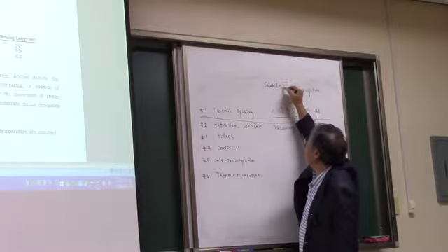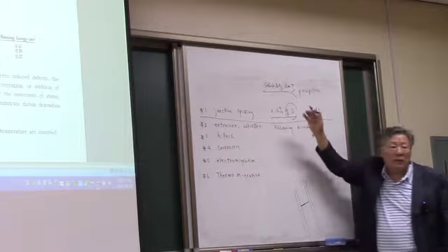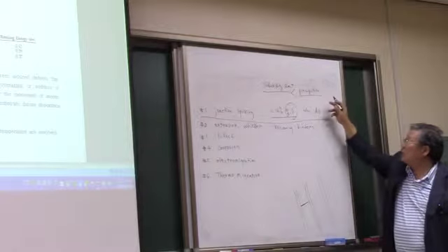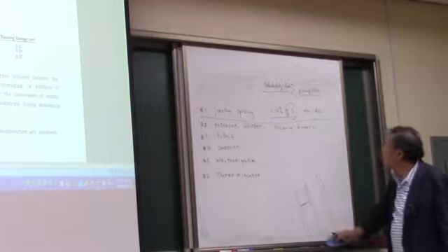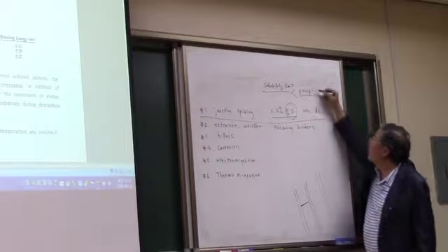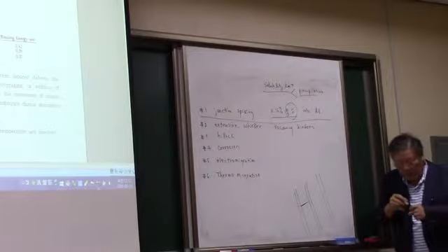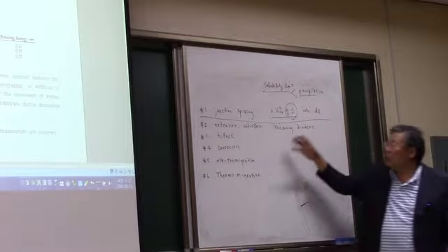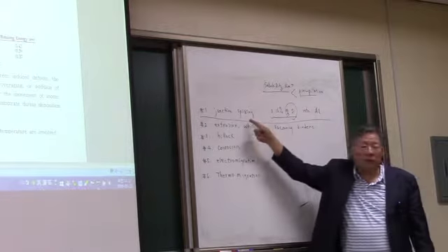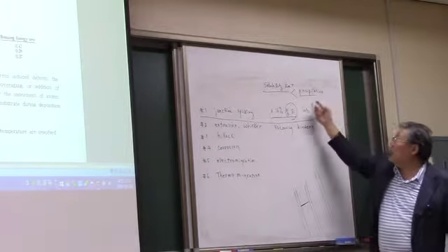If you add these things beyond the solubility limit, then you're going to have a precipitation, and these precipitations will not work to prevent the junction spiking anymore once it forms a precipitation.